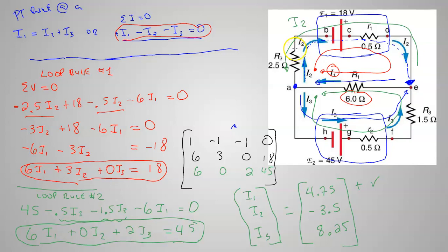It's okay. You just pick something. You guess that's the thing that made sense because the battery was pointed that way. So the current probably would go that way. Except this is only an 18-volt battery. This is a 45-volt battery. Much stronger battery. So as this current came around, most of it went this way, but some of it got jammed backwards through this battery. Right there, and that's going to kill that battery really quickly. So this is not a good circuit.